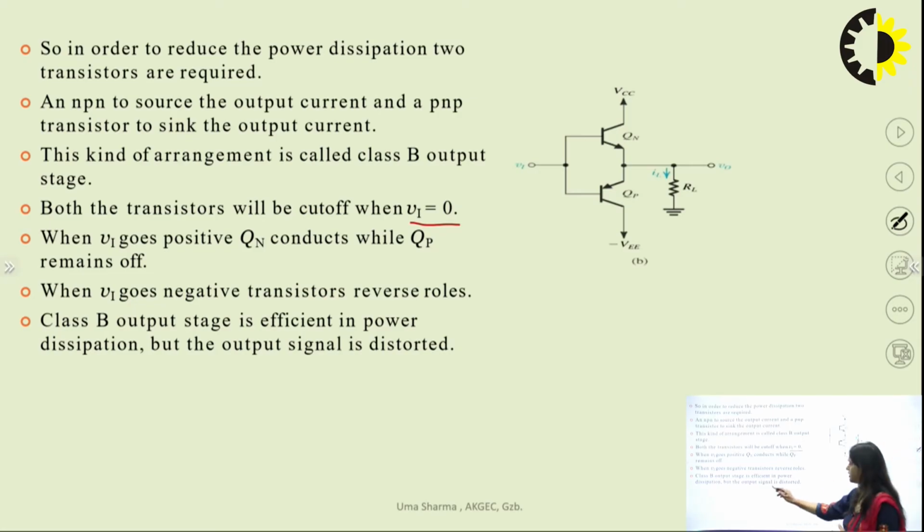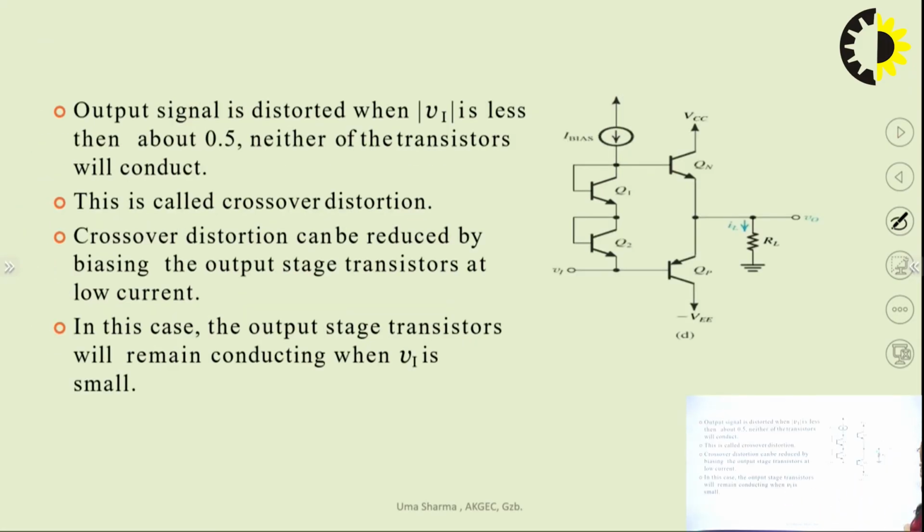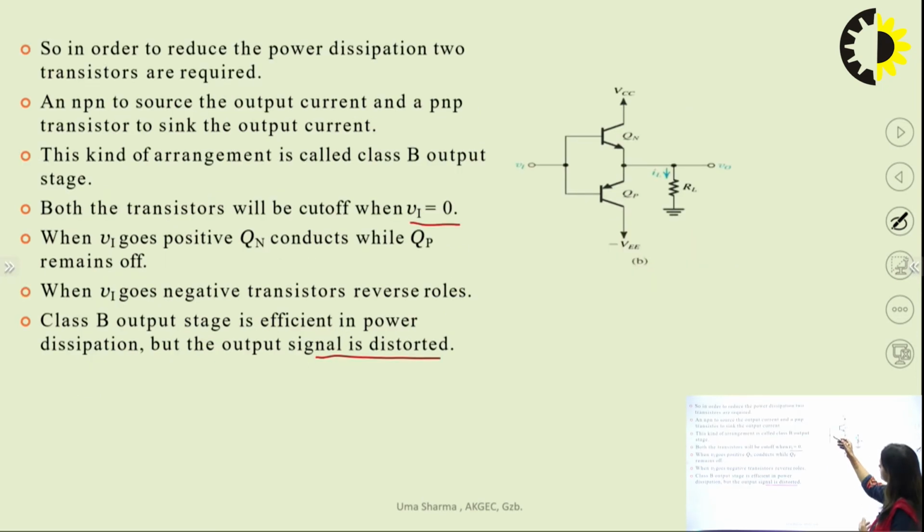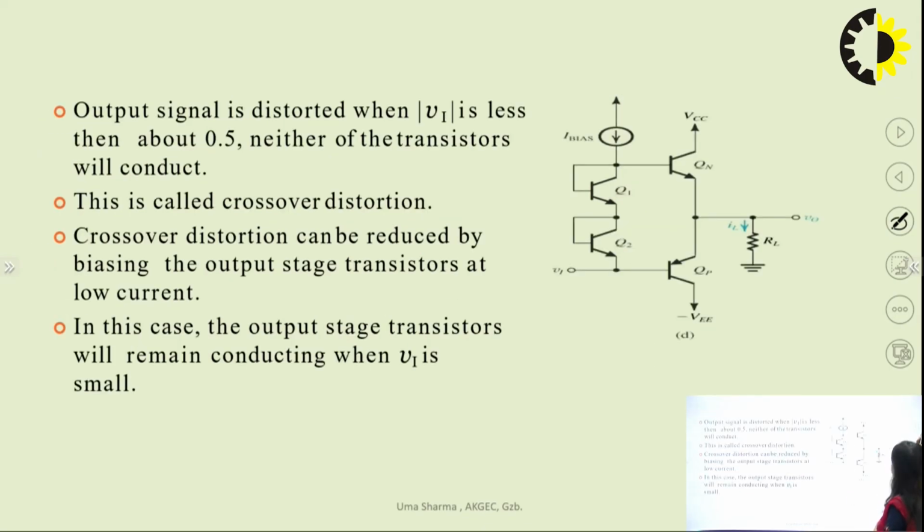signal distortion may be there, because whenever the input signal lies in between the threshold voltages of Qn and Qp, in that situation there is crossover distortion between the input and output. Due to this, the output looks like the transistors are off in this particular duration. So there is no output, although the input is available, because this input is not capable of turning on these transistors. That's why there is a gap in between two pulses. This is known as crossover distortion.